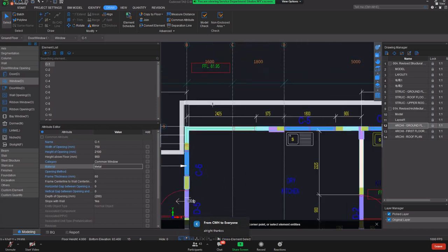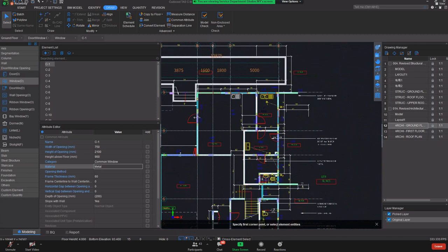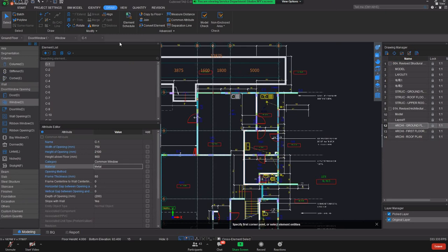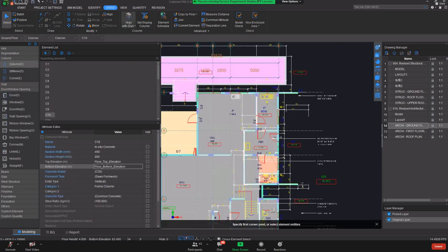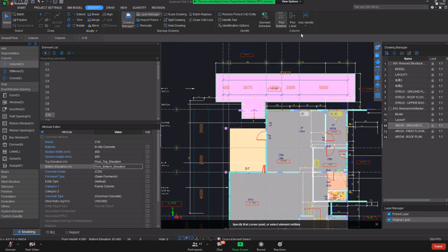All right. So yeah, I go back to my summary. Today we import the drawings, and then we scale the drawing, we split the drawings, and we relocate the drawing to the axis grid line that we have. And in the column, we use the manual method by using point and also rotation point to change the direction, and even F4 for the insertion point. F4 is not only for the column, it is applicable for all elements, right? And we also learned pick, sightline, label, identify for the column.